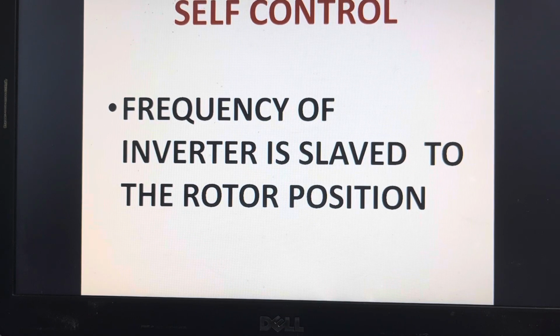This is similar to yourself driving behind a bus. So if you are on the two-wheeler, if you are driving behind the bus, if the bus speed is increasing, then you increase your two-wheeler speed. If the bus speed is reduced, then you also reduce your speed. So if you have self-control and if you are driving behind the bus, assuming that you cannot overtake, then you can maintain stability if the clearance is maintained constant. So we can maintain stability in PMSM if delta is maintained constant.